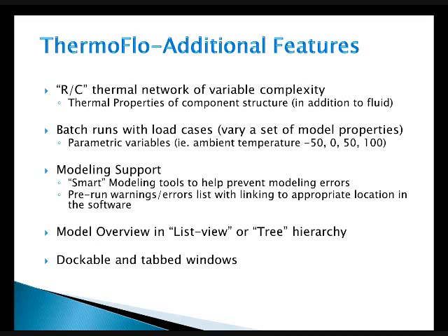Some additional features are that we also have an RC network. This is a resistance capacitive thermal network, so that you can represent any solid through a mass, and then have this tied through resistive links, and then that can couple directly into your flow bars for your fluid, and any fluid path will have an option to have a solid around them, and then you can tie directly to that solid or directly to the fluid, so that you can create fairly complex thermal systems and see their coupling